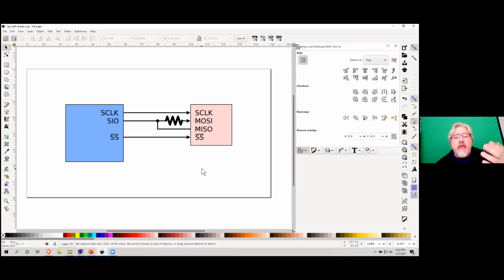And so, a use case that I've done many times, including recently, you may remember I was speaking about assisting my friend John with a target controller. And on that target controller, he has a joystick and several potentiometers that are read through a device called an ADC0838. It is a SPI device.